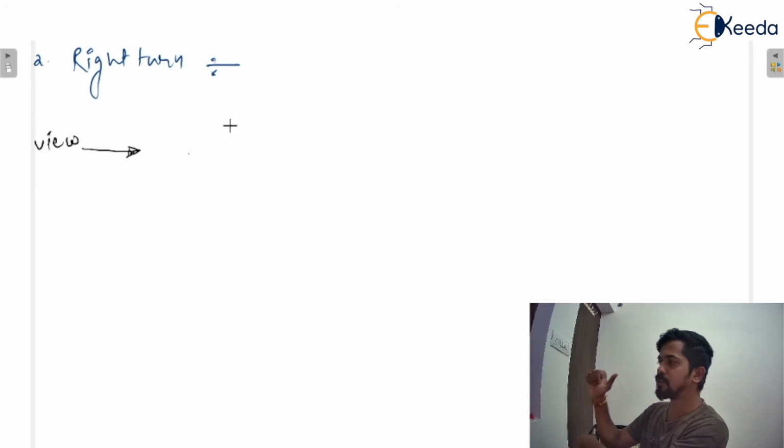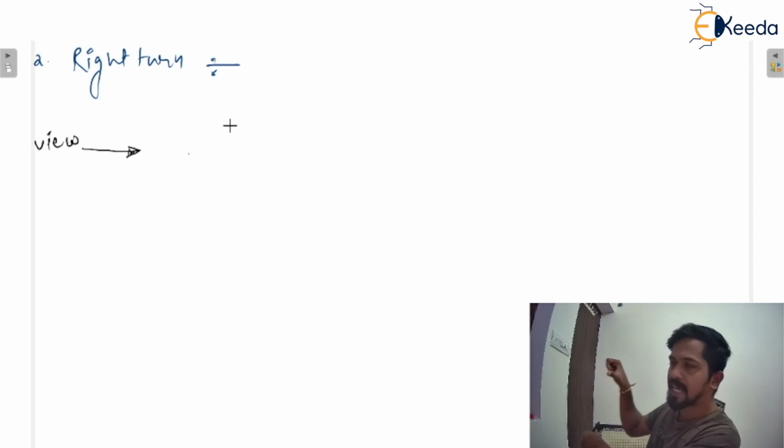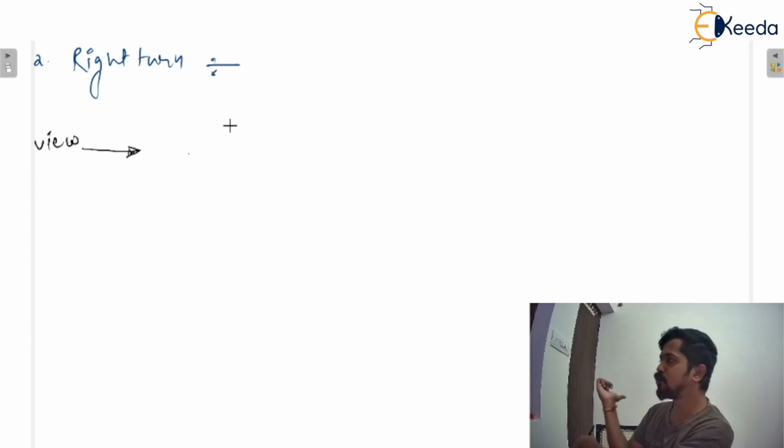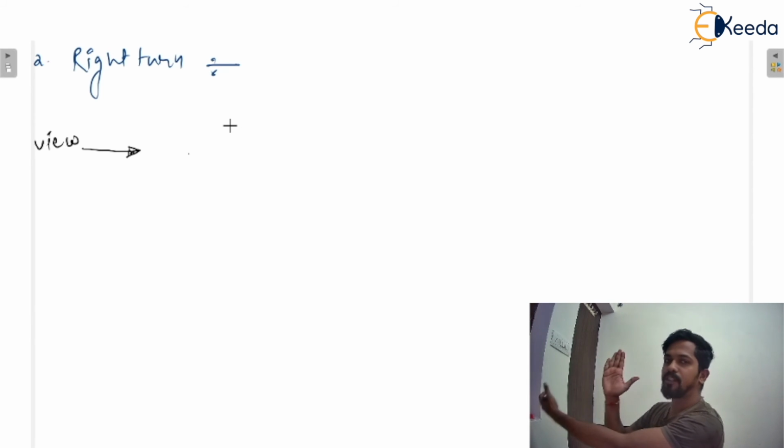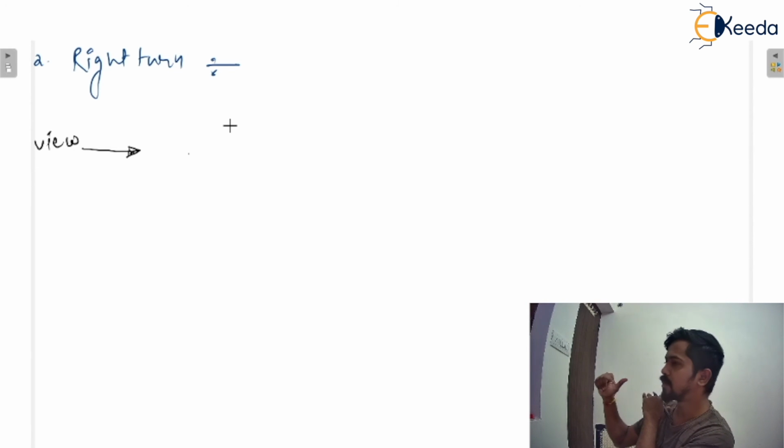So this would be the position. If this is the active gyroscopic couple, this would be the reactive gyroscopic couple, and you can see here, bow will move up. Again, I'm going to explain. I'm looking from the rear end side, and this is the front end of the ship, and this is the rear end. The engine rotates anti-clockwise like that, and the ship turns to the right side.